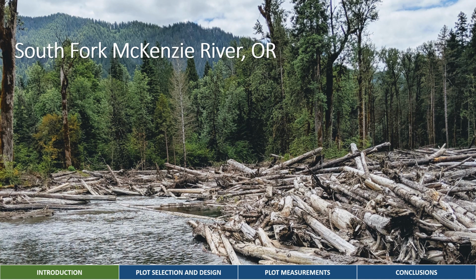Last summer, I worked out of the Pacific Northwest Research Station in Corvallis to develop the field-based monitoring plots at the South Fork McKenzie River Stage 0 restoration site. Stage 0 effectively resets the valley bottom, and the addition of wood creates the hydraulic and geomorphic complexity that benefit habitat. So the process-based restoration is allowing this wood to naturally fill out jams and create pools and naturally evolve to the anastomosing planform.